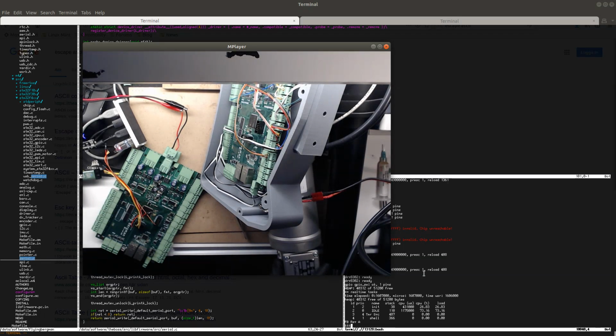Here's one servo, and there's another one behind here. This one is a cylinder, a linear actuator, and this one is a geared servo. I'm going to be controlling them with this control interface here, and they'll be connected to this board, and the control will be going over CANopen. So I need to have this encoder interface working.